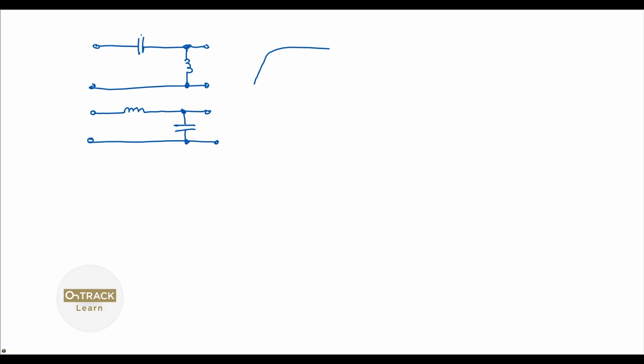So we know we can add capacitance by putting stubs. We can add inductance by adding thinner trace segments or trace segments that have a greater separation from the plane. Of course, we want to match impedance through the whole thing. So that's a low-pass filter. And to make a band-pass filter, you combine these elements together. So you would have series and parallel capacitance and series and parallel inductance. And of course, you choose the reactances of these elements at the corner frequencies you need to get the response you want.